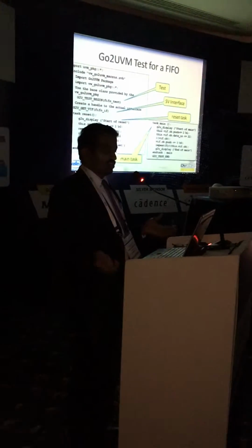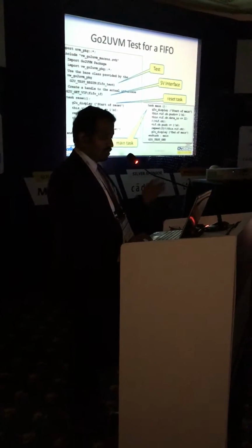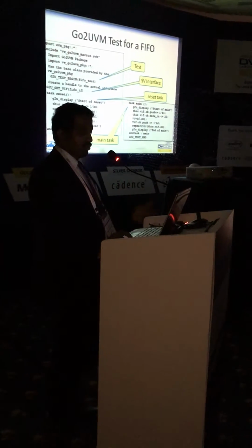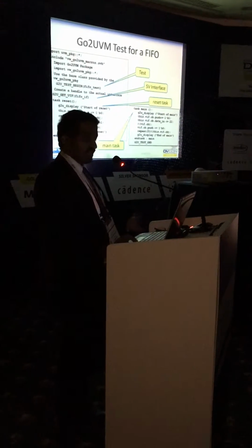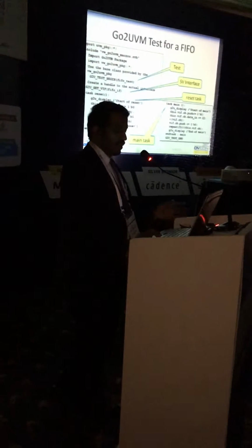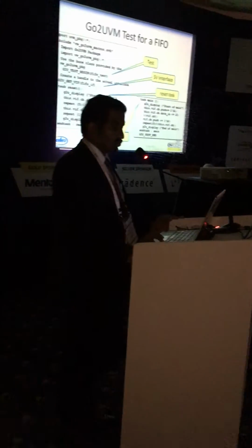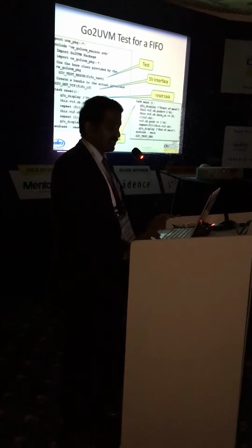And there's a reset, as I'm talking about, and there are other things like displays, smaller, low-hanging fruits. I'm not talking about it. Very high level. It's like your dollar display, but with all your UVM bells and whistles. And so you go and toggle the reset, wait for a few clocks, and then go and untoggle the reset, meaning set it to inactive state and come out. In this case, it's active low reset, so you reset 1 to be 1, right?